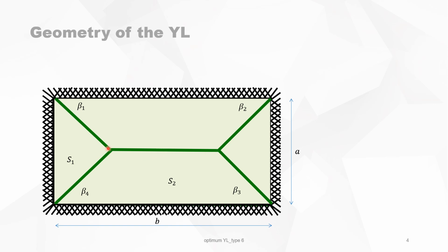This is not all. There are also the yield lines on top of the slab, which is for the fixed end support. All around, you will have also a yield line. We assume that the maximum bending moment on top is equal to the maximum bending moment on the bottom of the slab.